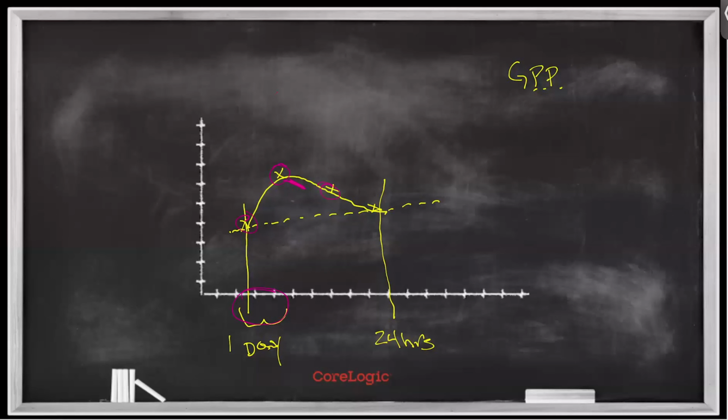You take one when you get there, figure out where you're at, mark that down, write that information out. Install your drying system, let your dehumidifiers warm up, let your environment acclimate to what you've installed, which usually takes 15, 20 minutes at the most. And then once that is established and your dehumidifiers have gone into a full dehumidification cycle, then take one more reading approximately 20 minutes later, right? And all of that can be within the context of a 1 hour window.